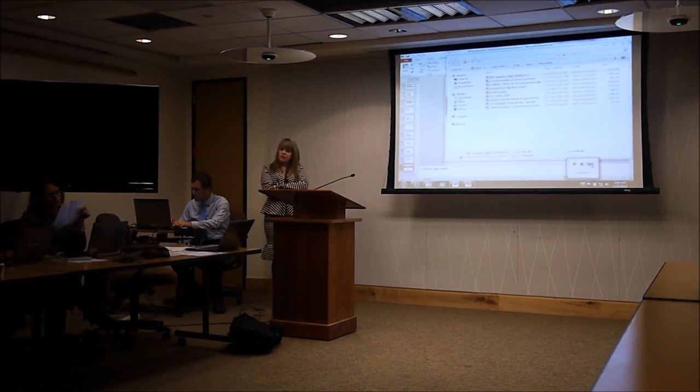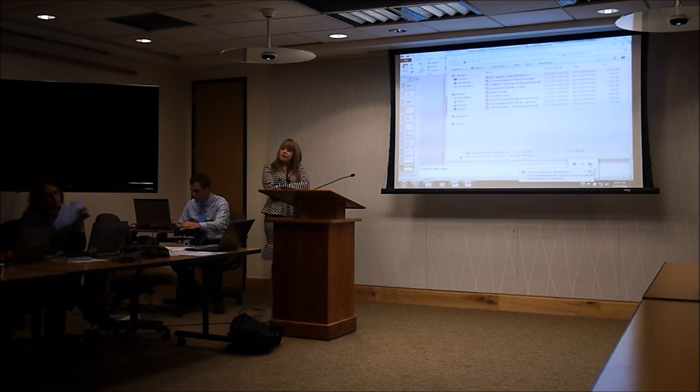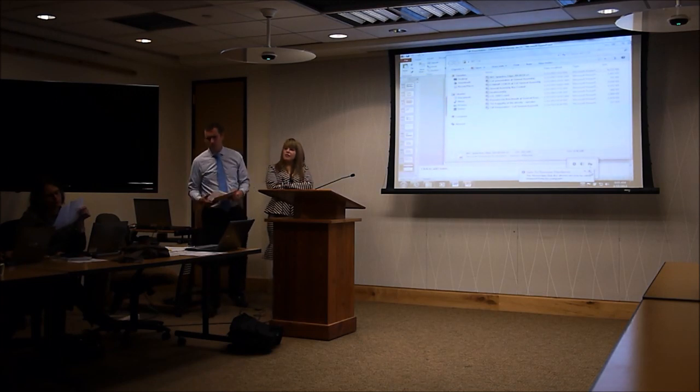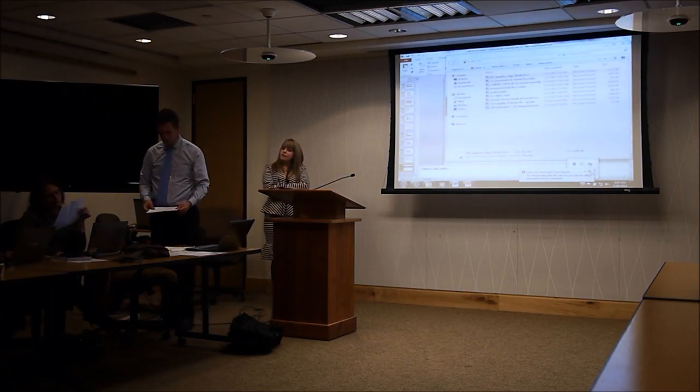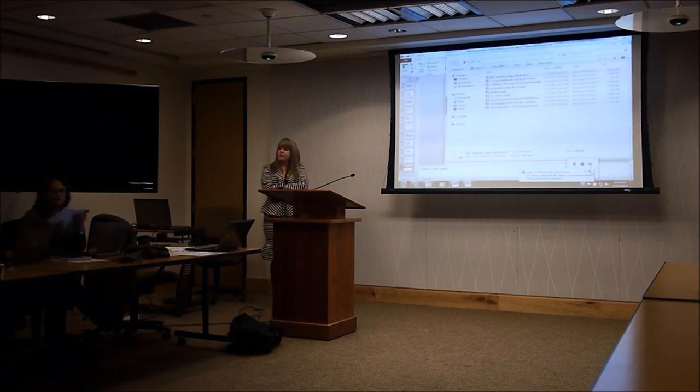And the fourth point is, in terms of the intense situations where we get to BRT, I think you have three contexts. One is where you have a single route running at very high intensity. There, headway management is extremely important. The second is where we have very intense operation, but on multiple routes whose individual headways might be 4, 8, 10 minutes. That is a completely different situation. It's more capacity management, where you have at least some more flexibility in headway management.